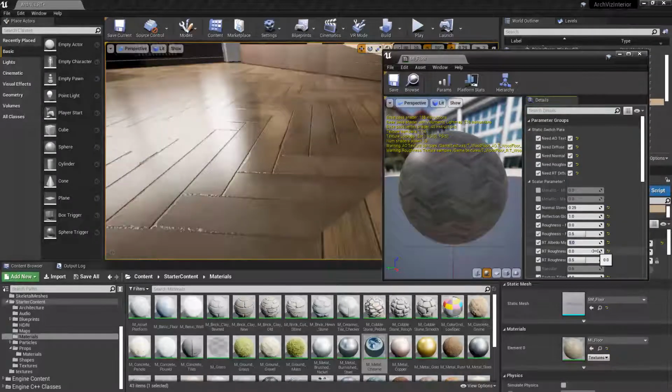Let's go ahead and change this down to number 1. And now you can see that the texture in the reflection looks a lot more like the original texture. Now as I step up in MIPS, you'll see it slowly but surely get blurrier and blurrier. This technique is really good for saving on performance. Using a lower level MIP map means you're going to get more cache hits on your ray traces. And cache hits are basically just saved information on where the ray hit and the color of the pixel. Let's change our MIP bias to a value of 3.